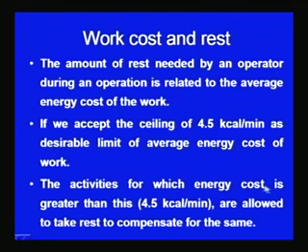For activities whose energy cost is greater than this upper ceiling limit of 4.5 kilocalorie per minute, rests are allowed so that the body can recover by consuming the accumulated lactic acid while doing jobs which require a higher amount of energy.